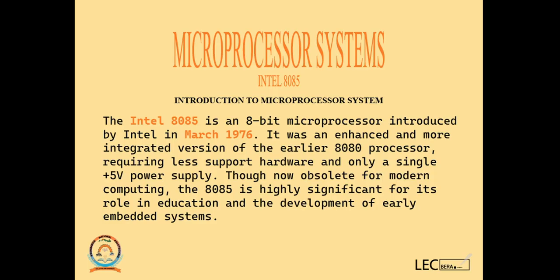What we say it's an 8-bit microprocessor. It's an 8-bit microprocessor because it's going to process 8 bits of data every time it does execution of that data. So whether we are moving data from the memory to the arithmetic unit, or we are moving it from the arithmetic unit to registers, we are going to move this data in 8-bit.